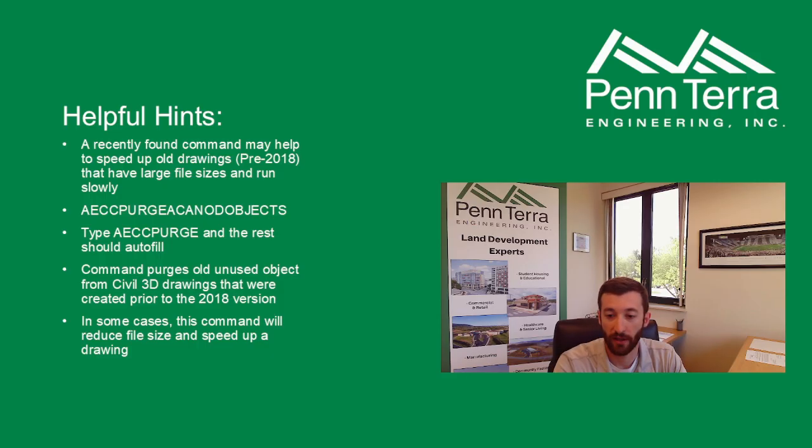There's an issue where some files of that age have old objects in them that seem to multiply themselves in the background and make your file size really big and bog things down, even though they're not really doing anything. If you have any drawings that fit into that category, give it a shot and see if it helps. I've tried it on a few older drawings and it definitely made the file size smaller. I haven't had any that were really slow to try it on yet, but maybe someone will, so give it a shot.